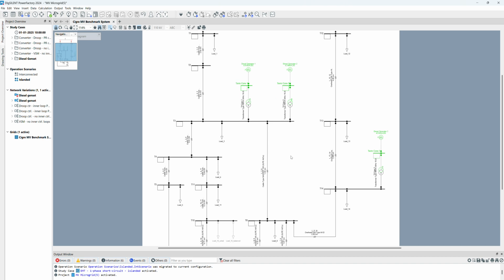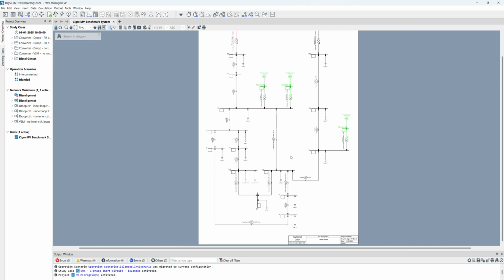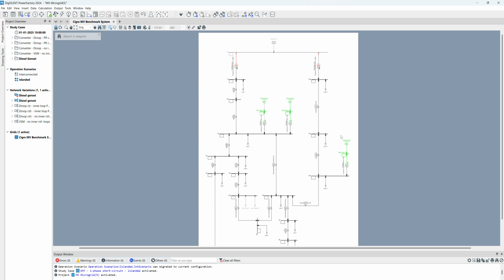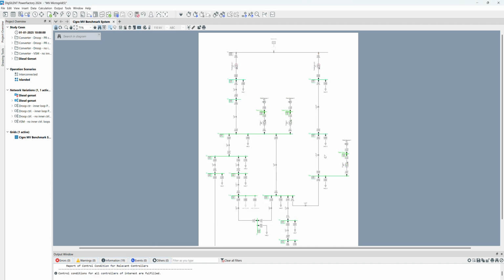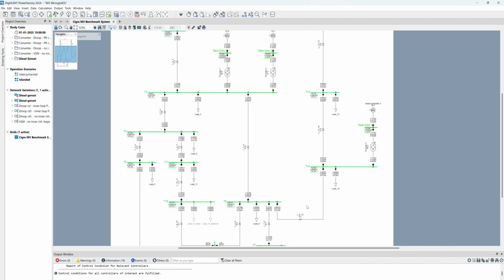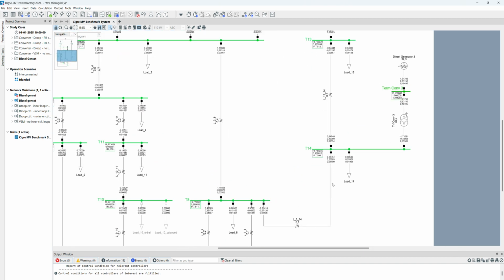So here in this example, we have a couple of generations, and when we say microgrid, it can be connected or disconnected from the grid. It now is disconnected because of these two empty boxes. If you make a load flow here, you can see the current flowing on each line. And we want to, for example, install one fuse on this line. Here you can see the value of the current that goes through this line. For example, now it is 11 amp.